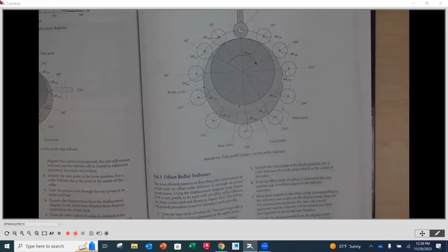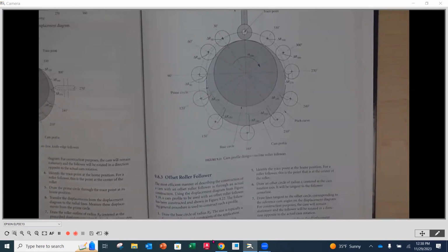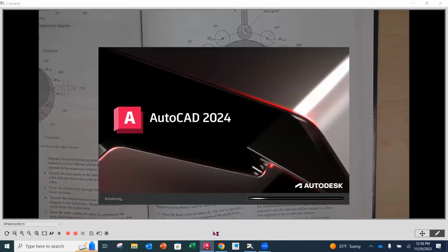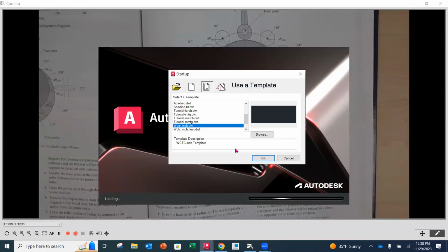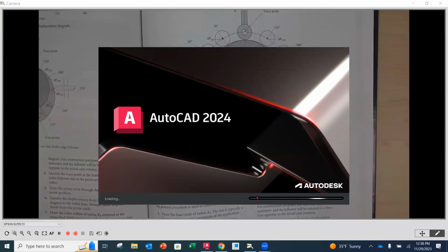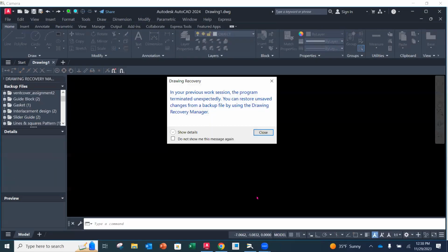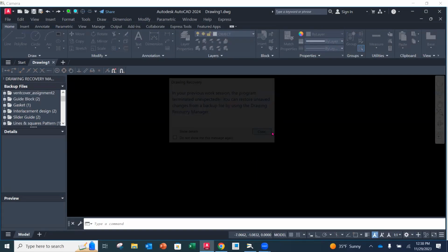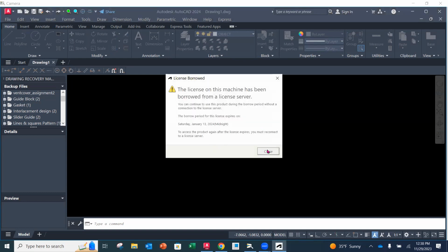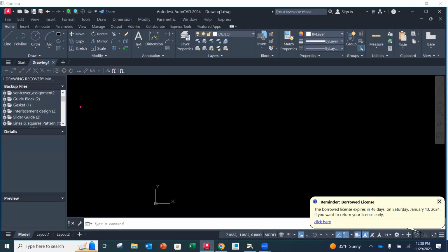Okay. So if you're in AutoCAD, and I don't have my AutoCAD open, oh well, maybe I'll open it up here. That's a good question. So you want to use a spline, you don't want to use an arc because arcs are only like 2 or 3 points. So let me open my AutoCAD first. I'll show you where the spline is. And this is what you would use for the displacement diagram as well, when you find those points along the X and Y axes.